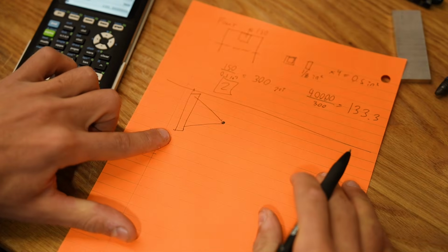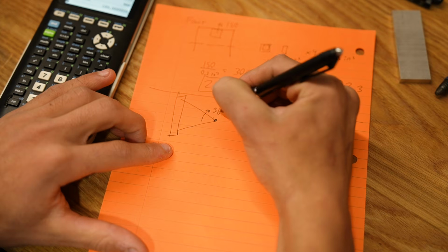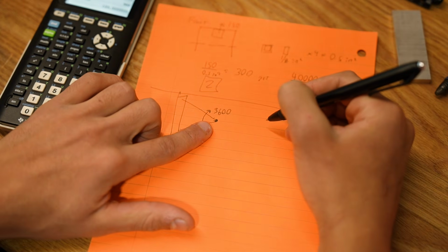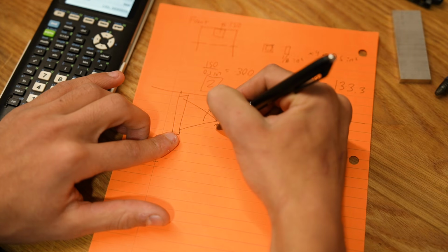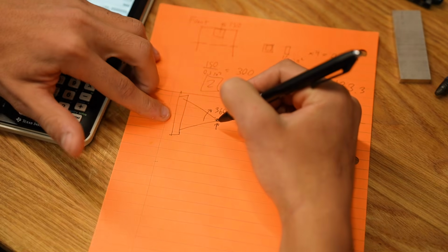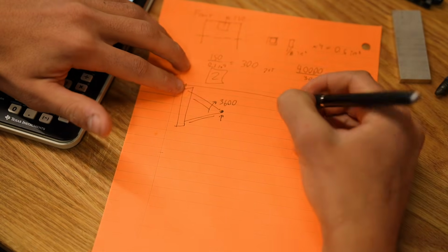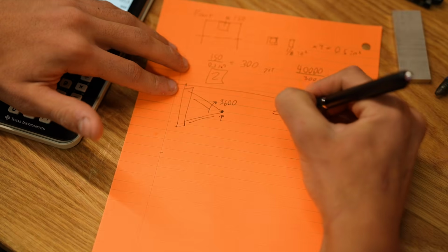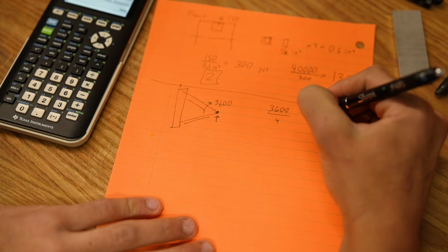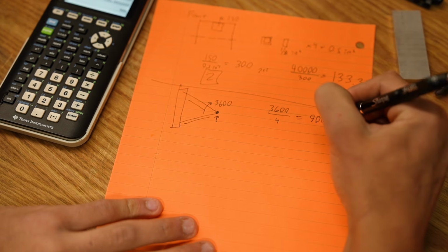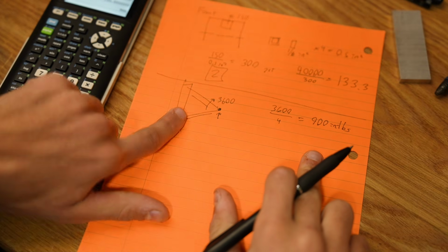In this case, looking at the side view of the robot, we are trying to resist a 3,600 inch-pound bending moment about the rung and transfer that to the rest of our robot. We're sharing that load among 4 different profiles. So we're going to take 3,600 and assuming load sharing, we find that we get 900 inch-pounds of bending torque in each member.